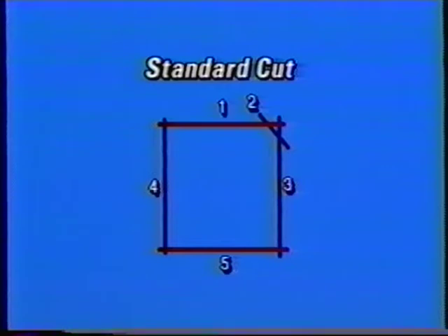If the roof is walkable, a power saw may be used. Make sure the roof surface is clear of debris in the area of the cut. Have a rough outline of the hole in your mind before cutting. The most common cut is the standard cut.